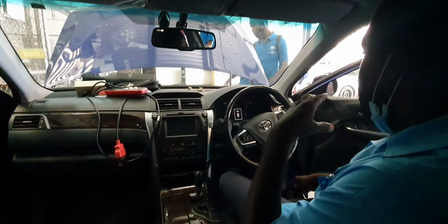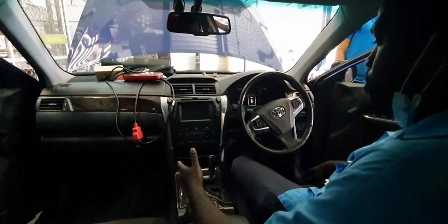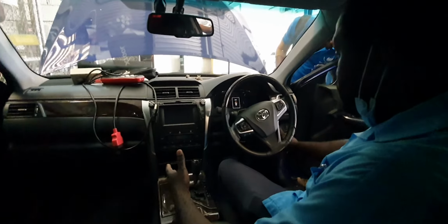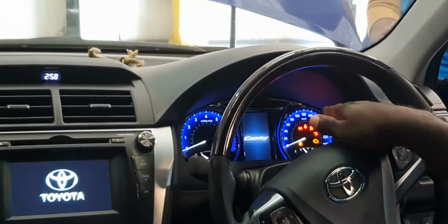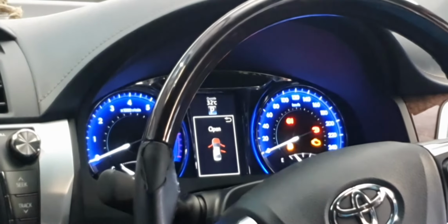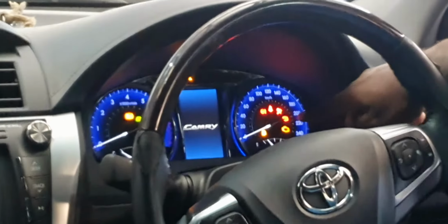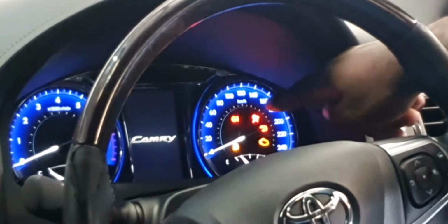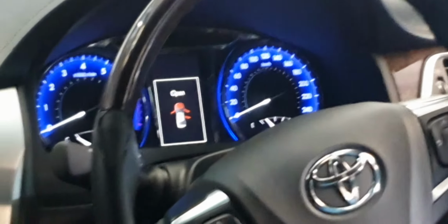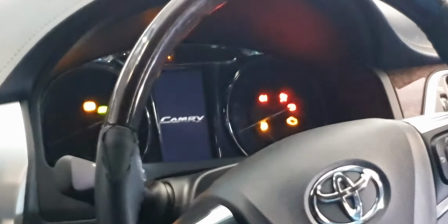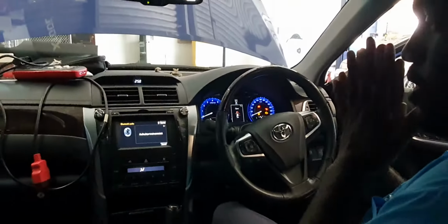Yeah. Alright, so first, whenever we're working on any computerized control circuit, electronic control circuit, motor vehicle electrical, here we have our instrument cluster. And all of these lights that we're seeing in our instrument cluster are controlled by their own module. We see the engine check light, the supplementary restraint system light, the EPS light, this is a fuel level. If I turn on the park light again, look over this side, we have the ABS, skid control, stability control. So all of these lights operate by a car computer.